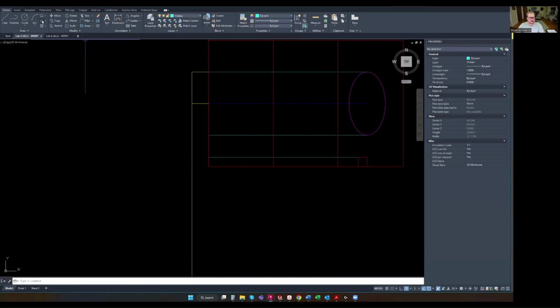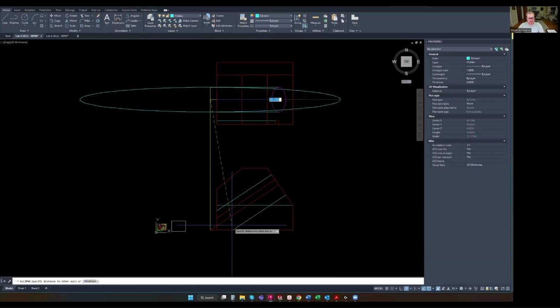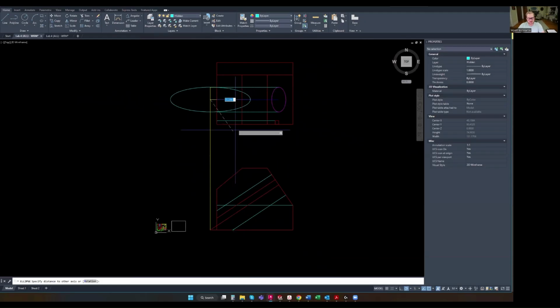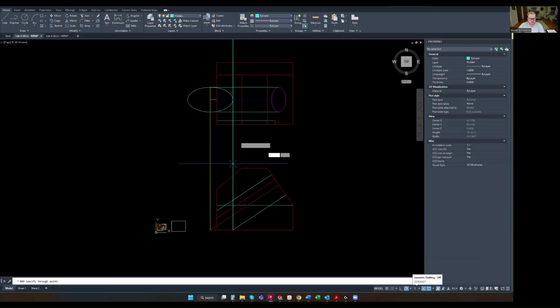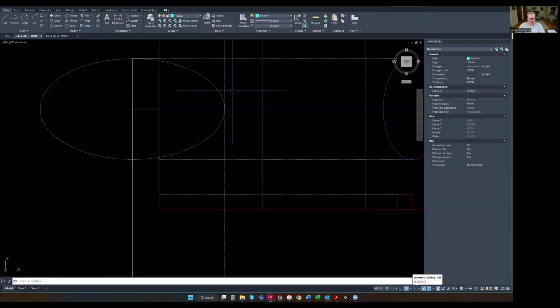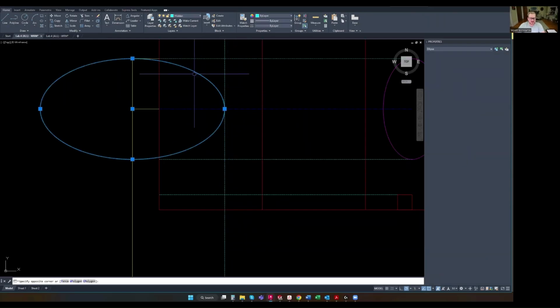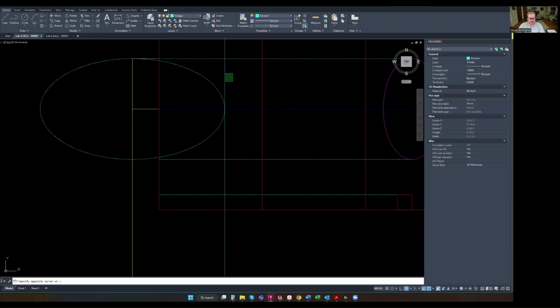We can grab our ellipse tool, start at our new center point, out to extent here. And then actually I accidentally deleted the line that we need here. So I'm going to go ahead and snap to it that way. If that doesn't work for you, if nearest is still on, what I just did will not work. Alternatively, what you can do is just create a new vertical construction line and then snap to that point, just like that. That's totally fine.